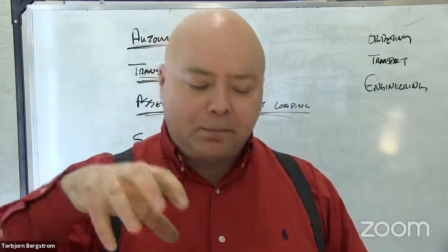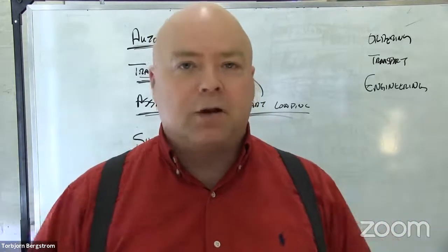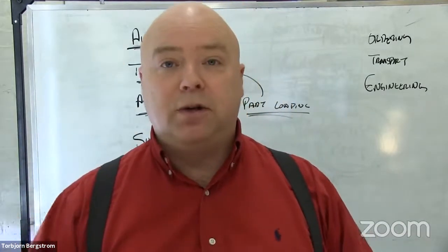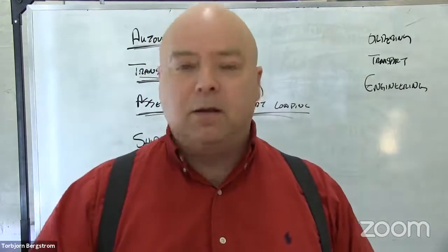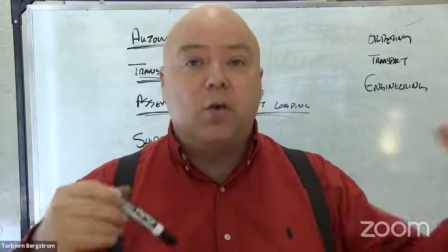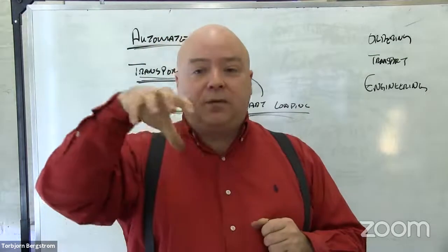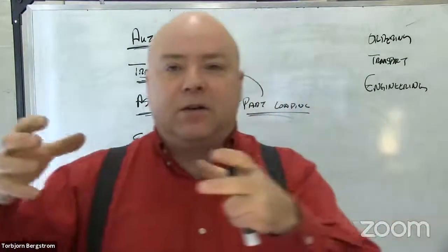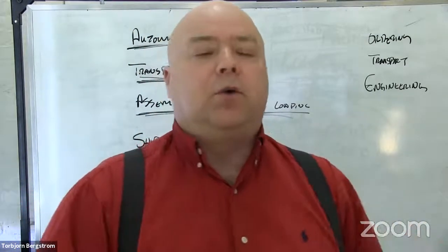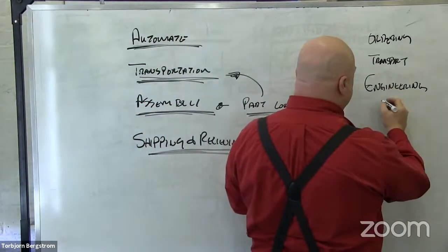And you literally plug it in to SolidWorks, Creo, whatever solid modeling software you're using, and you click the button, and maybe it says, which machine tool do you want to use? And you say, I want to use the mini mill. And it says, do you have the standard tooling in stock? Or maybe it knows, actually, Esprit can know whether or not you have the tools in stock. And it can figure out all of the different tool paths. It can be programmed to do all that stuff that we had you doing in class to learn about the process. So you can automate the toolpath creation.